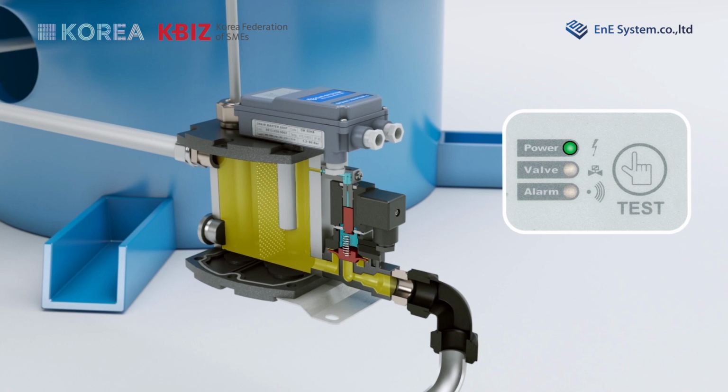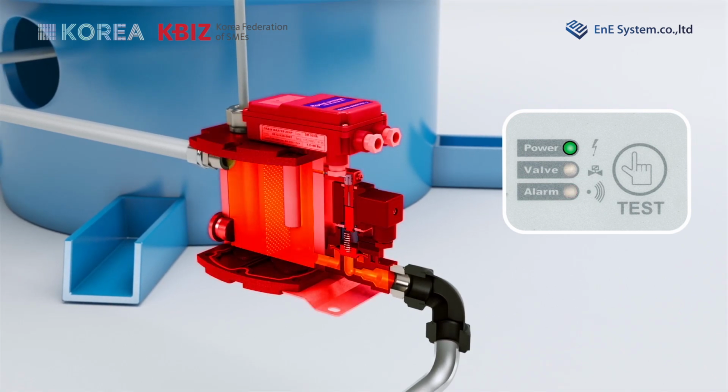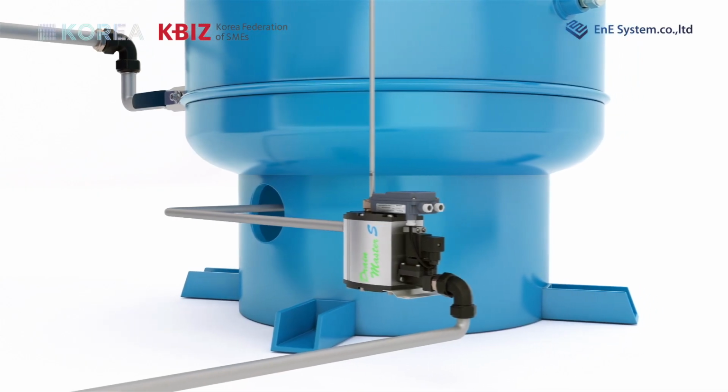If condensate is not discharged for 60 seconds due to scale, etc., the situation is notified to a user via an alarm signal, which initiates the automatic restoration mode for normal drainage.